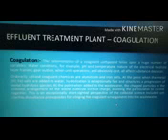Water conditions, for example pH and temperature, nature of the electrical double layer formed, equipment design and unit operations, and of course cost all affect chemical choice. Commonly used coagulant chemicals are aluminum and iron salts.